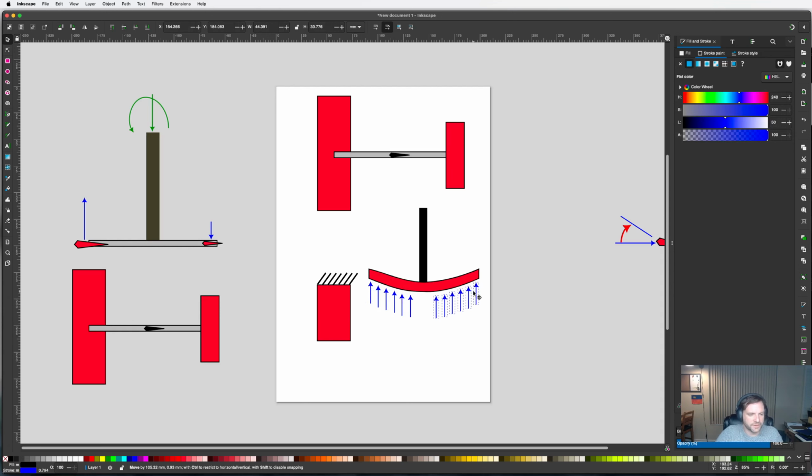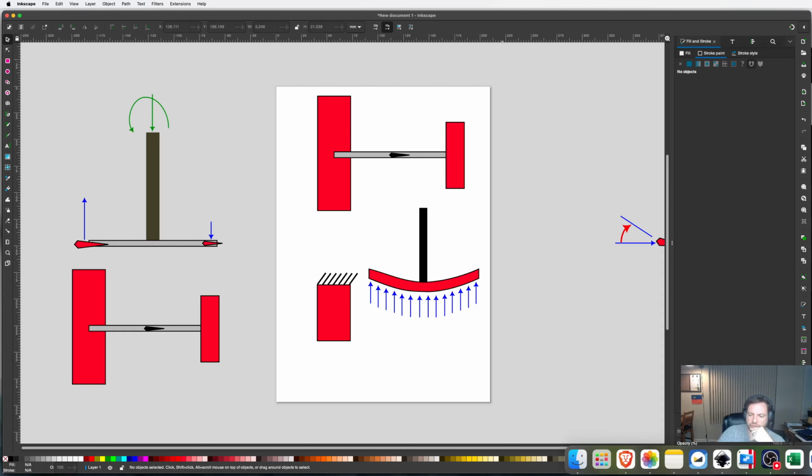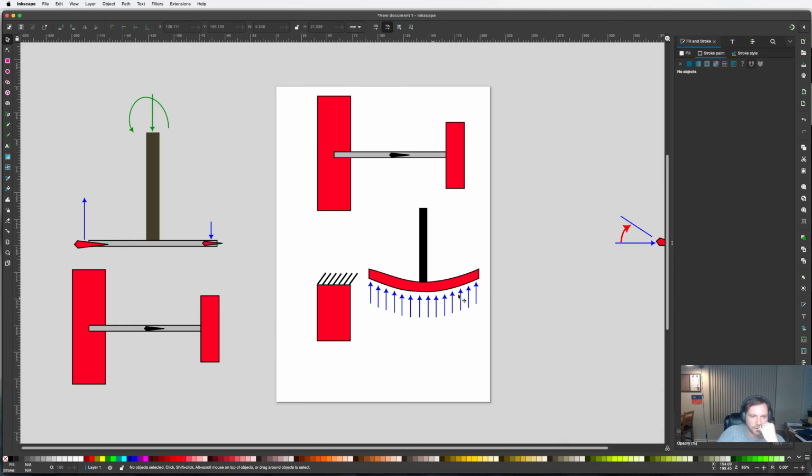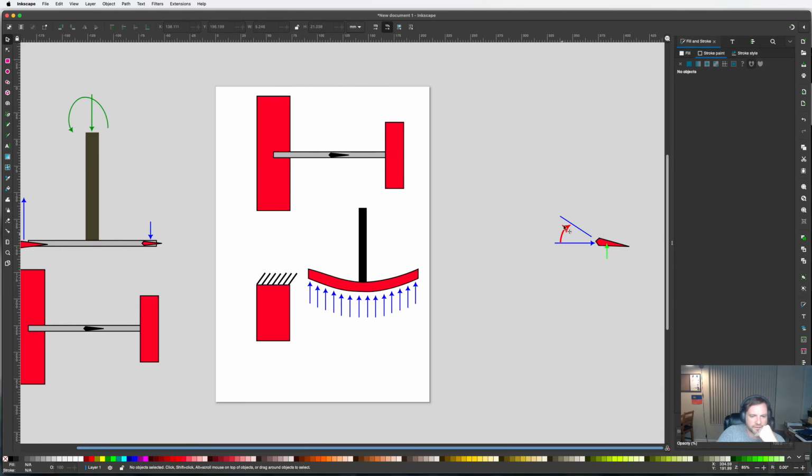And in reality, it's not, because we're making a lot of approximations this first time around, and it's good to be aware of that. Part of the problem is that when we make this approximation like we did before, we used a simple formula where the coefficient of lift is equal to 2 times pi times the angle of attack of this wing, where the angle of attack we showed before on the side here.